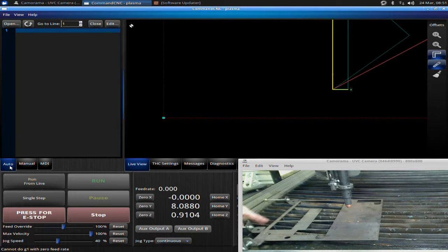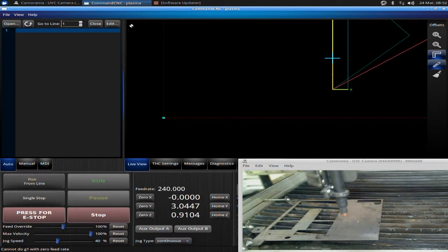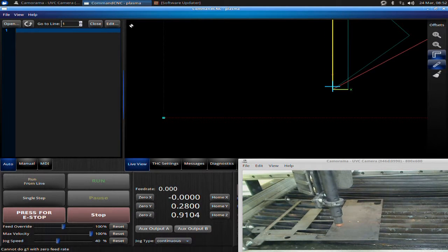One of the biggest things you want to watch out for with these stops is if you cut really close to the edge, you can come along and hit the edge with the torch, and that can mess up your part. So you can rotate them downwards so that they don't stick up above the edge of the plate. Okay. So if your plate moves and you don't have it against some physical stops, you're kind of out of luck. But let's talk about some other ways you can lose position.